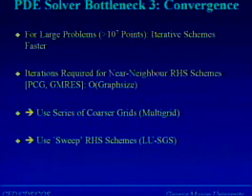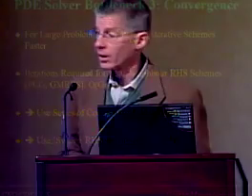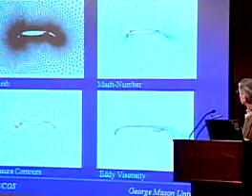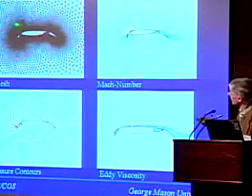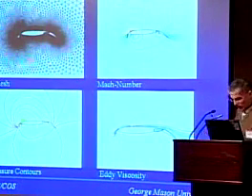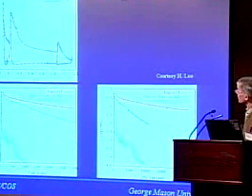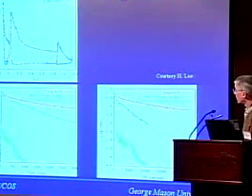So the idea was to use a series of coarser grids like multigrid, or to use sweep right-hand side schemes like the LUSGS scheme. And I have one case here. This is a landing configuration. You can see here, I suppose that's the Mach number. These are the pressure contours. This is the eddy viscosity. This is a very fine mesh here with boundary layers and everything on it. And this is the comparison to the experiment.